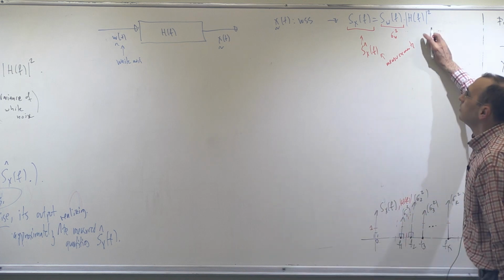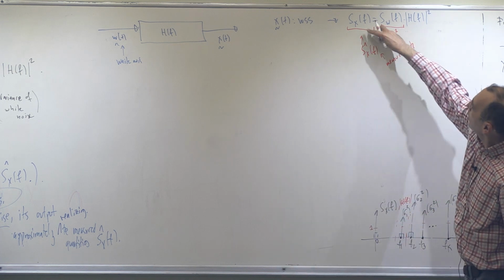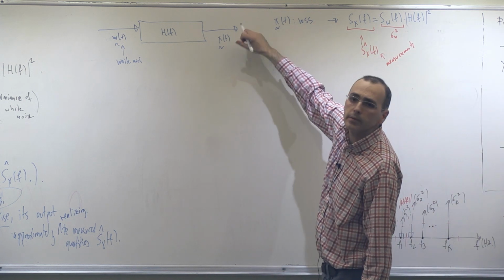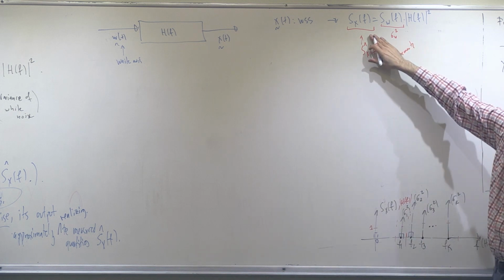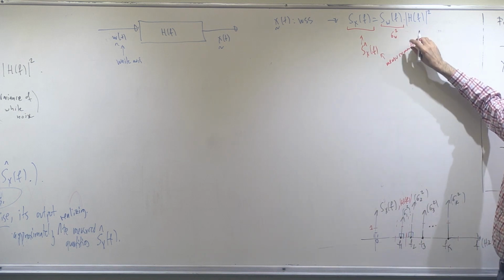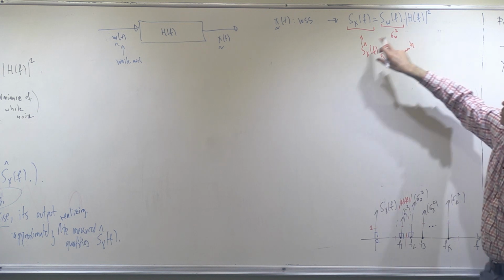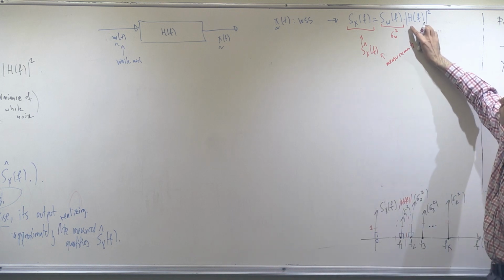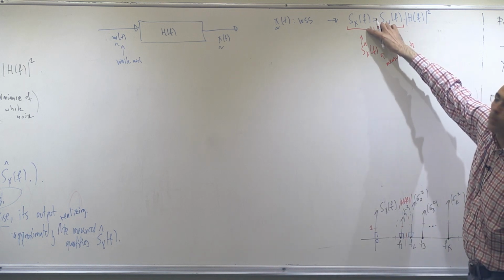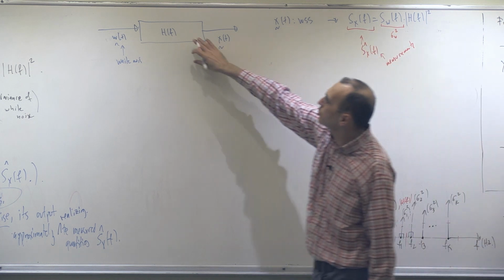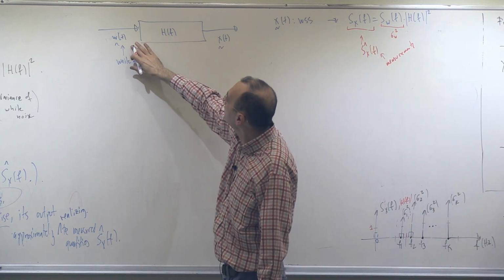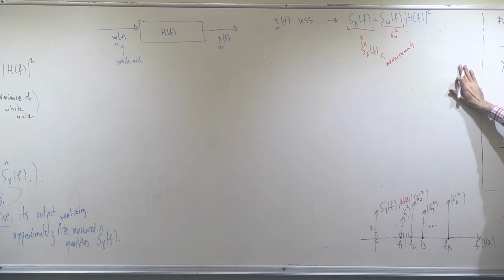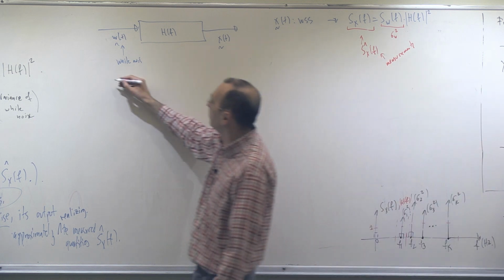Then this is called the synthesis problem. If you have some measurements for this, how can you generate or understand this process? You can say that this process can be modeled by matching the power spectral density. This is my measurement, and this is the white noise. Essentially, I'm trying to find a filter whose magnitude square is equal to your measurement. If I can design such a filter, even approximately, that means I can synthesize this random process having the same power spectral density. This is called the synthesis problem.